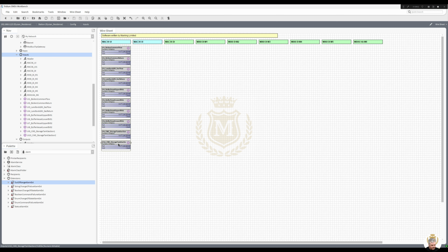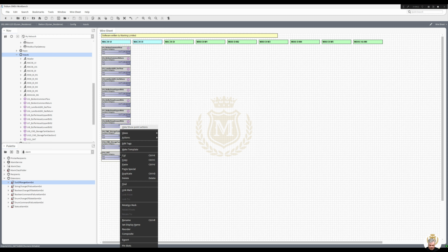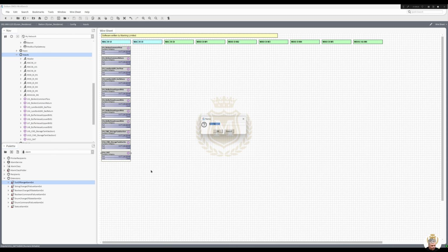Outside air, next done. 11 OAT. OAT is not going to get to -50 or whatever, so we know we're going to be okay with the alarm there. Reception space temperature is 12. Reception space.